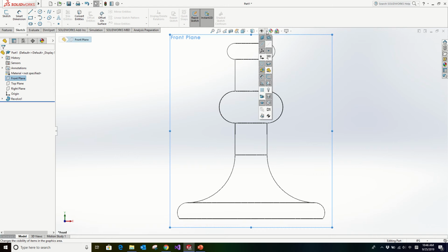You just click on here, and there are different options. Basically, we are looking at the view temporary axis. Click on it. Then you will have a symmetric axis over here. Actually, this is the axis we revolve about, right?